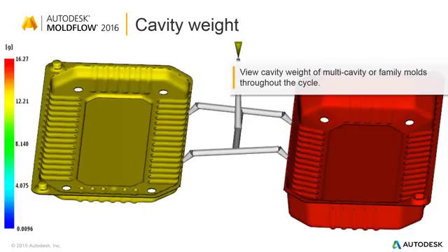And this can help you look at making sure that the cavity weight of your multi-cavity mold, for instance, is evenly distributed. And if not, then it's probably worth looking into why the imbalance would happen.